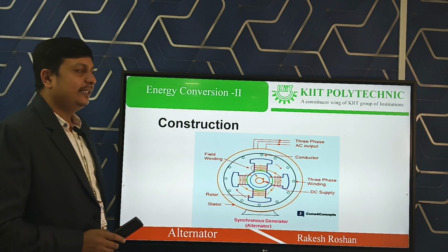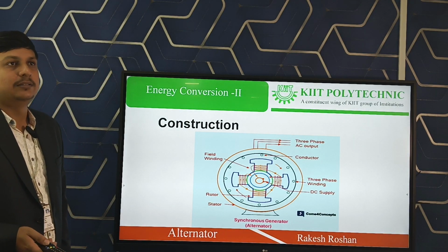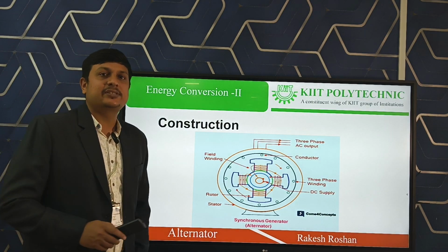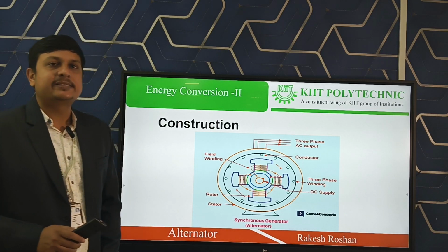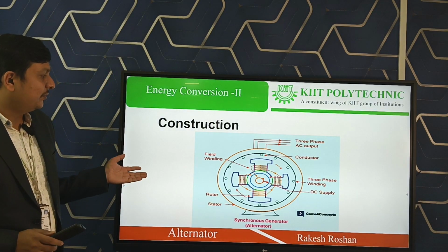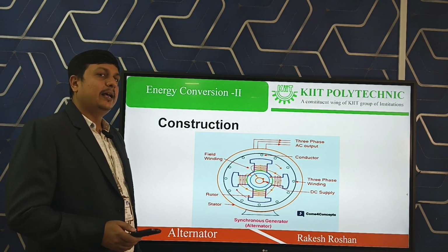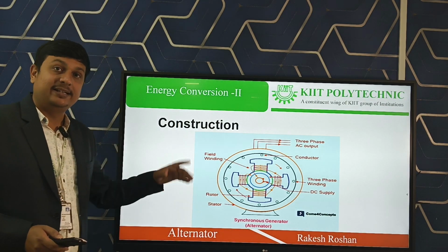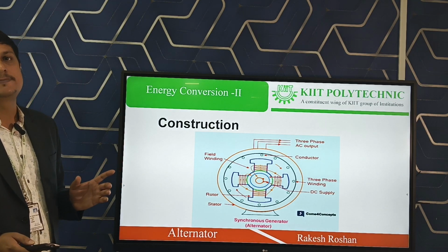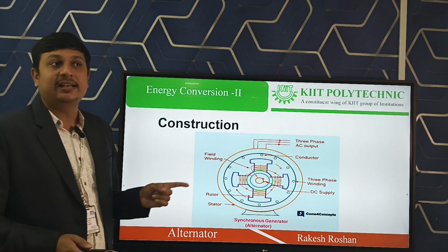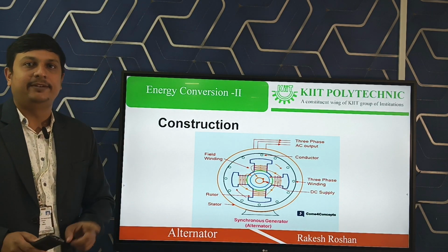What are the advantages of a star connected armature winding? This question is generally asked in laboratories, viva and interviews. The first advantage of a star connection relates to design: as I told in an earlier slide about the rotor, we provide insulation as per voltage rating. And as we know, in a star connection, phase voltage is 1 by root 3 times the line voltage.